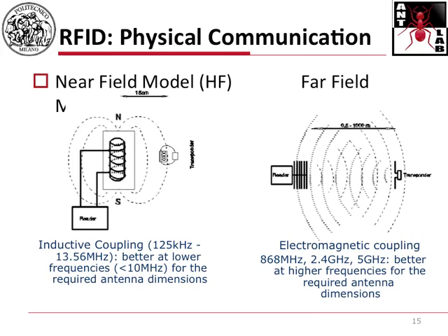Clear? The principle of far-field coupling, which is electromagnetic coupling, is more or less the same. The difference is that in electromagnetic coupling, we are using also the electric component of the field. So we're not using only the magnetic field, we're also using the electric component of the field. This means that the type of receiving circuitry at the tag is slightly different. It's no longer a coil. It's something, let's say, more refined. But still, the effect and principle is the same.